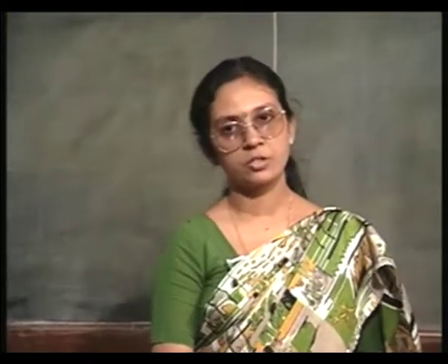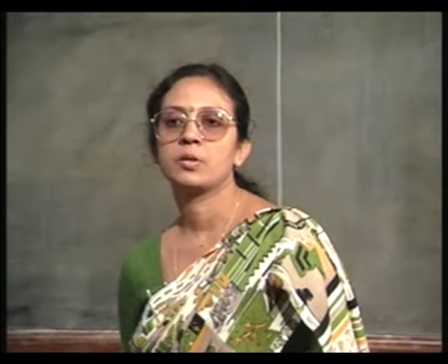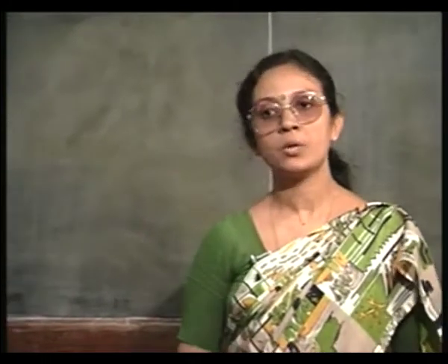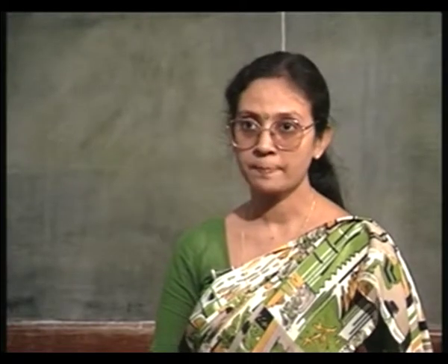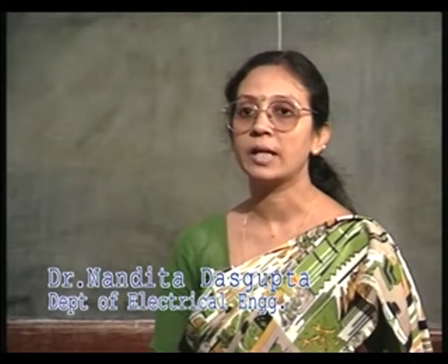In our discussion about VLSI technology, so far we have discussed the crystal structure, we have talked about crystal growth, we have talked about epitaxy, and we have also talked about oxidation. So, now you see physically you have your substrate material. By bulk crystal growth you have grown a bulk substrate material. If necessary, on top of that you can also grow an epitaxial layer, and you have grown an oxide to cover the surface of that crystal.